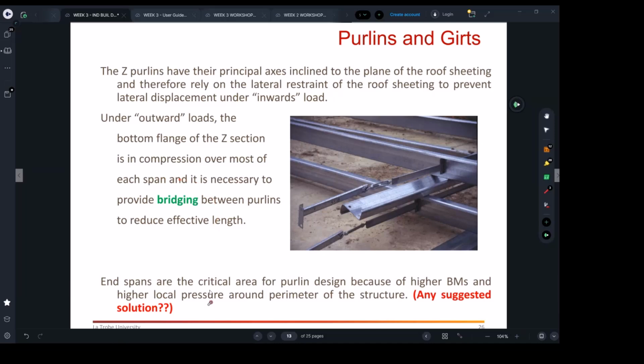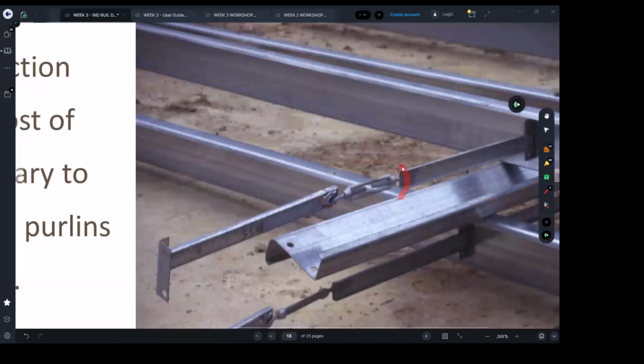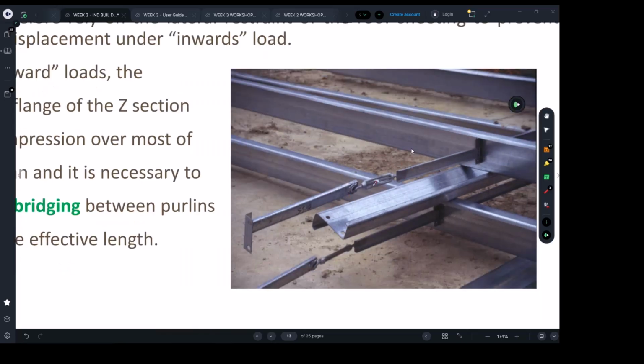Okay, and that was the question I was answering already. So bridging is just a piece of steel which helps prevent buckling. Usually, when you build this, even if the engineer said put them every 900 or 1 meter, they won't get it perfectly. It will be off by, say, 1 centimeter or a few millimeters. So you can't really build the bridging in a single fixed length. You would do a lot of cutting and that's costly work. So it is adjustable in terms of length to make sure it fits a lot of situations.